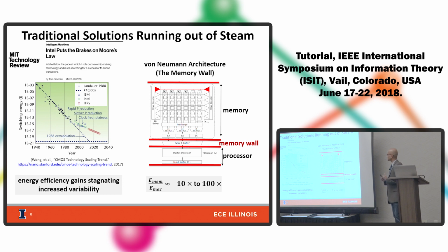And this has always created a problem for computing in general, because you have to read a lot of data. To do computation, you have to read data from memory, process, and provide the outputs. And this reading of data from memory consumes a lot of energy. In fact, recent estimates show anywhere from 10x to 100x for on-chip memory. If you go off-chip, these numbers become even bigger, 500 to 1000x, which means you read 1 byte of data from memory, you bring it in, and you already have consumed 1000x more energy than the energy required to do multiply add on that byte of data.